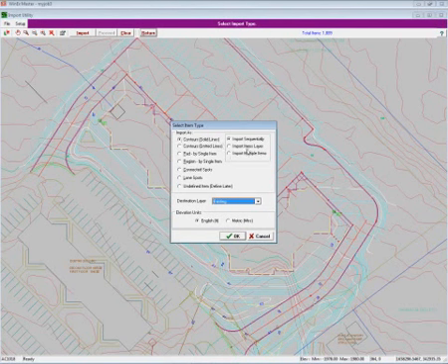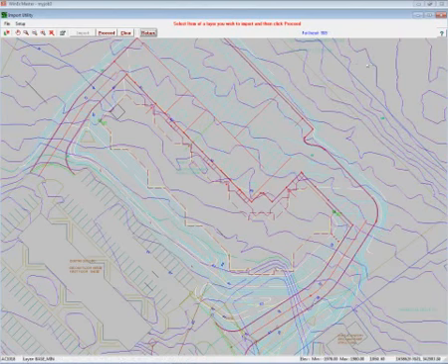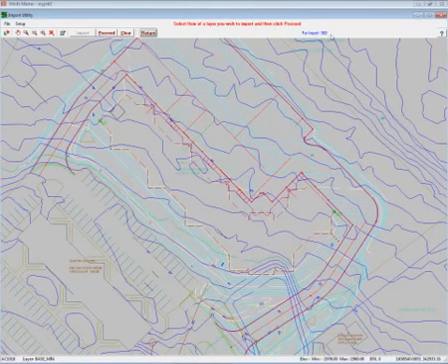I'm going to use solid lines. And because it's a CAD file, which is made for engineering, I'm going to bring everything in by layer, because about 99.9% of the time, you're going to get a good layered CAD from the engineer. And we'll bring in the existing first. I'll hit OK. Now all you need to do is click on one of your existing lines, because we did say we're bringing it in as a layer. So we'll click on that, and you can see it lights up the whole layer in blue. There are 368 topos here. And I'm going to click Proceed.